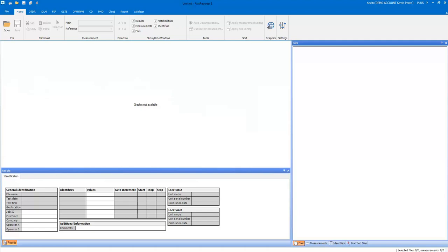So Google Drive is full with all the bidirectional iOLM traces, the OLTS trace that contains the span loss and ORL, as well as the CD-PMD from the FTB 5700. And so all of this information is populated in there. And of course, we can automatically refresh that, or we can manually input this data, right? We don't have to sit here all day long and let it auto-refresh.